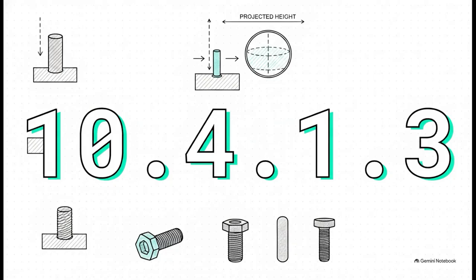Or you can use advanced CMM software simulation that mathematically extrudes the measured hole's axis upward. Now, there's a really subtle but absolutely vital distinction in the standard when we start talking about studs and pins versus your standard bolts. If you are detailing a drawing with press-fit dowel pins or studs, paragraph 10.4.13 of Y14.5 dictates that your specified projected height has to equal the maximum permissible height of the pin after installation.